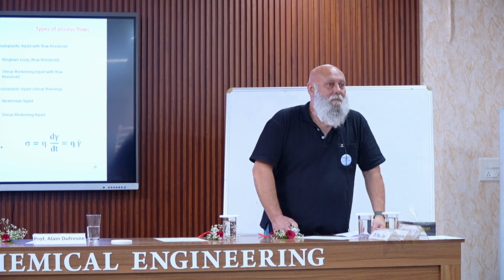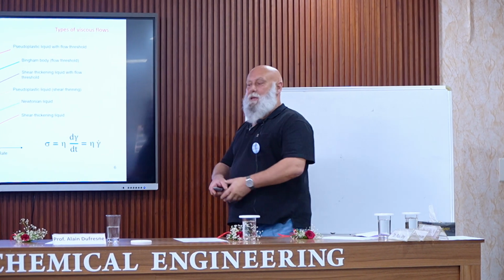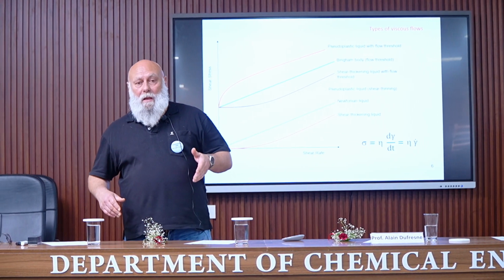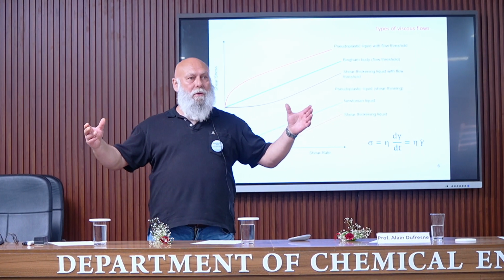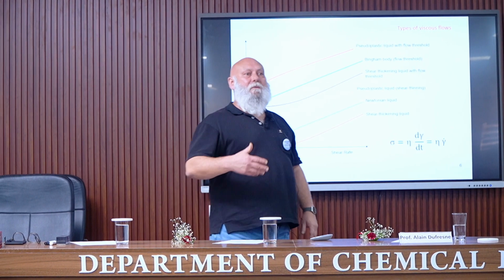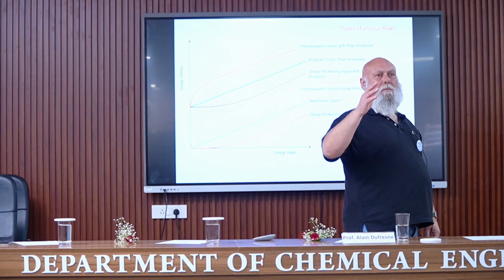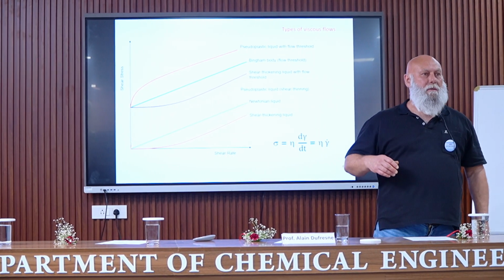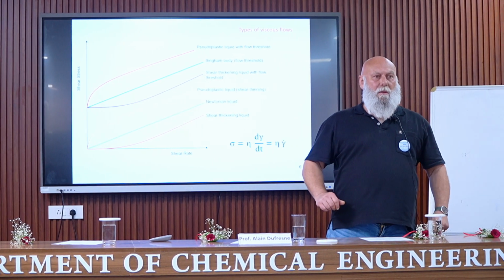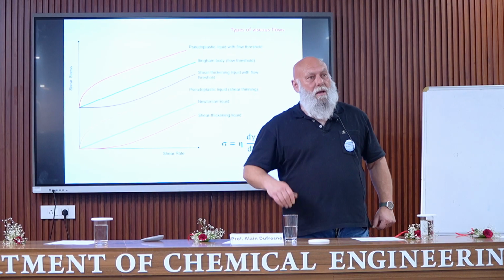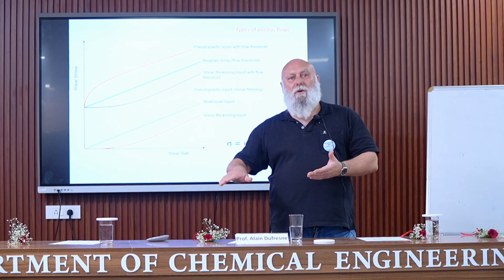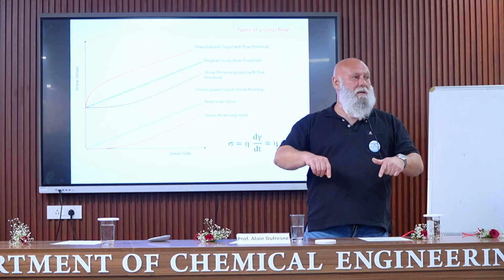The reason for this is that we are considering long macromolecules in the liquid state, meaning that these molecules are flexible, and they are in the form of what is called random coils. And when applying a shear stress to this material, we can, in some conditions at least, have an orientation of the macromolecule. And because of this orientation, the viscosity decreases, because we can also have some disentanglement between the macromolecules.